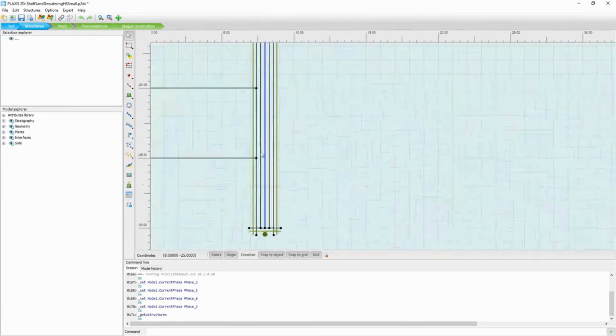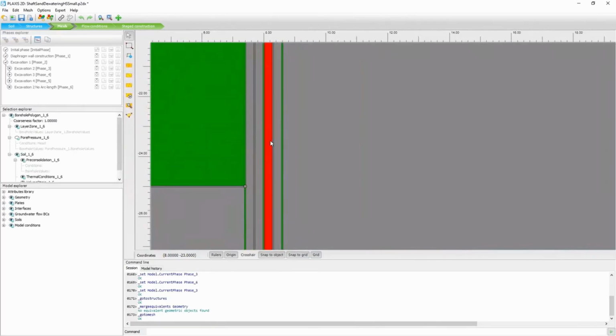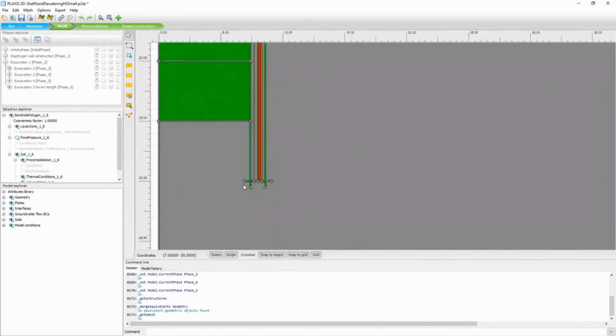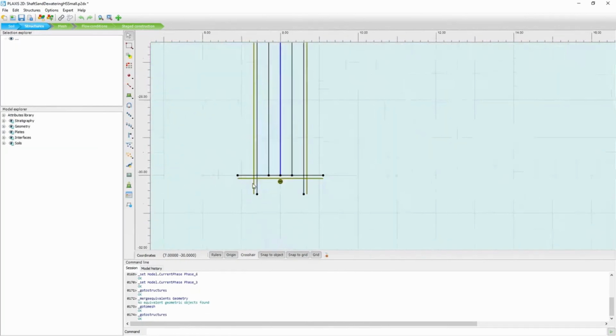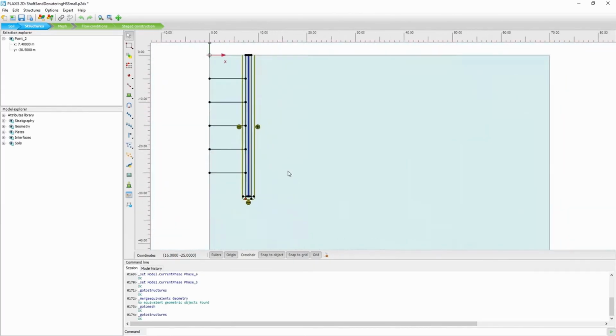You see the way I have sliced this cluster here, enforcing the mesh to follow, and this way having enough elements through the thickness. I also included the extension of the interface elements slightly into the soil. And in terms of geometry, this is basically it.